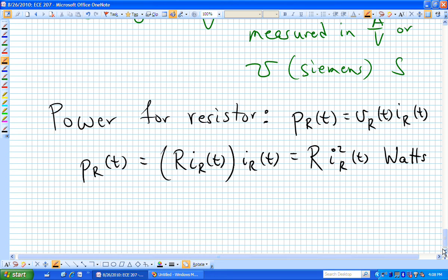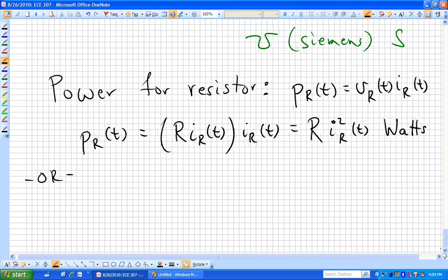Which, if you have a toaster, you probably just have a heating element in that to brown your toast or to make your toast a little darker. And we've agreed that that's roughly 1 kilowatt. So if you know now how much current you're drawing from that toaster, you can figure out the resistance of that heating element from this relationship. P is equal to I squared R. Or you may know the voltage across that resistor, and you don't want to break your circuit or tear it apart to try to measure current.